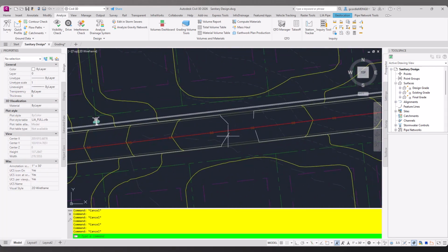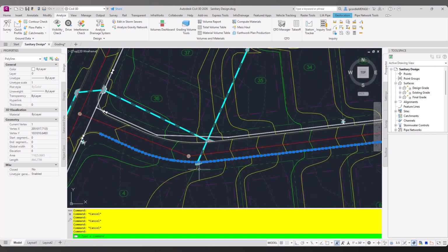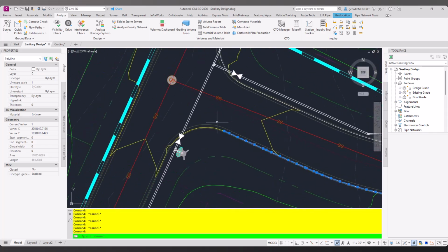Now let's analyze this one here. So if I select it, I'm going to take a look at it, and yep, water goes into our single wing catch basin, but it stops at this point. And the reason why is because there is a low point that's right in here somewhere. You may not be able to see it. It may not be perfect.